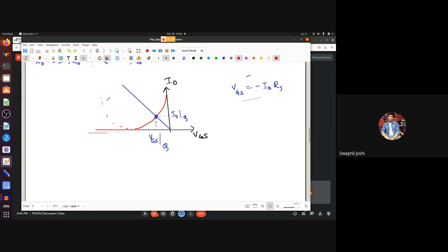Yes, sir. And now let's compare what would happen if you were to change the JFET so that you have a slightly different curve. Say, this orange curve is for another JFET which you have replaced your original JFET by. Notice that the quiescent point values are things that you want to maintain. So I'm going to compare between the fixed bias circuit that we had a while ago and this one. For the fixed bias circuit, to get this VGS at the quiescent point and this ID, what you would need is basically a VGG which is equal to this in size, or minus VGG, and this is what the fixed bias circuit would give you.